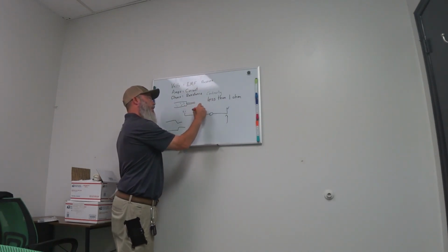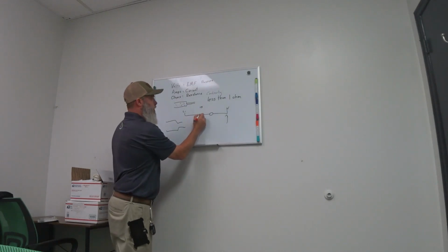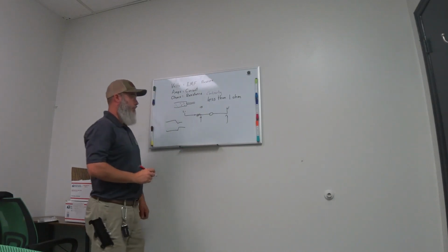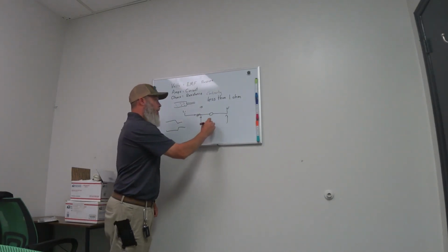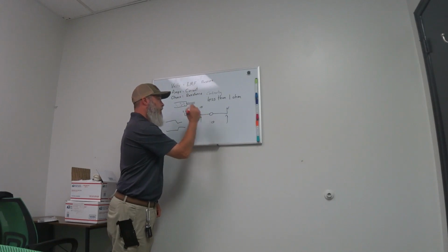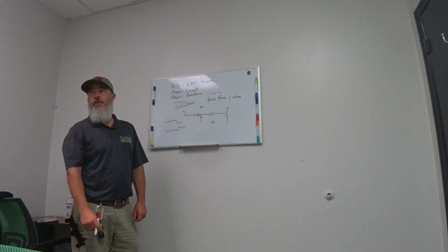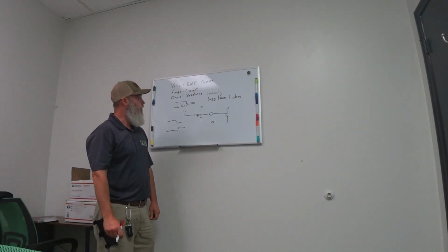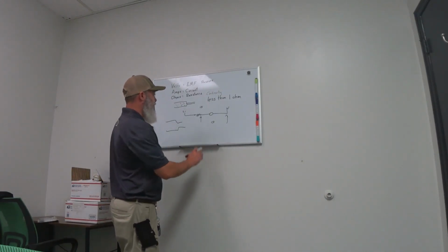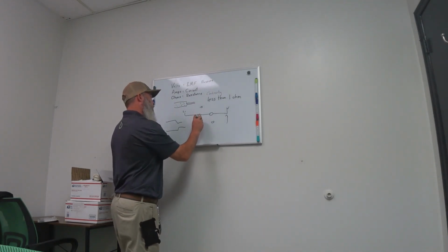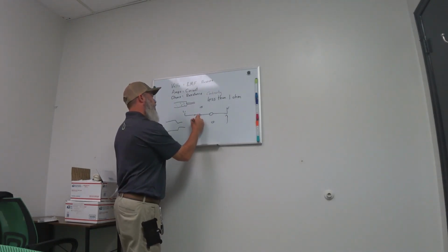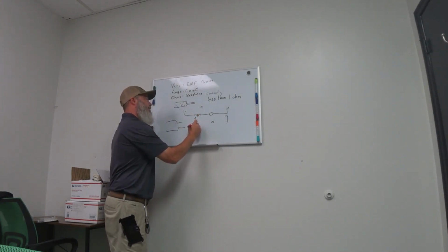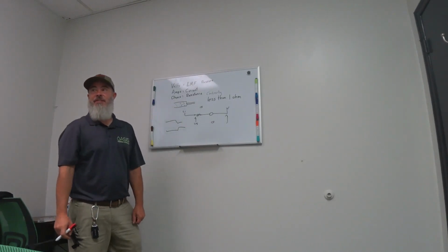Then you put a lead here, and you've got 0 volts, nothing, and you're like, well, what could that possibly be? So then you put your lead here. 115 volts. It's the switch.